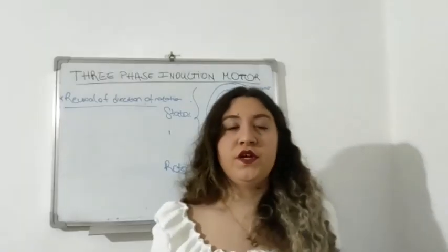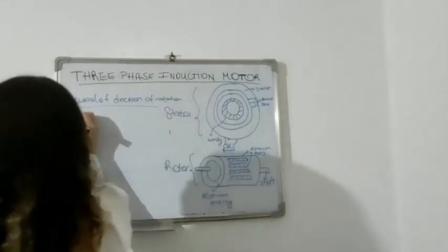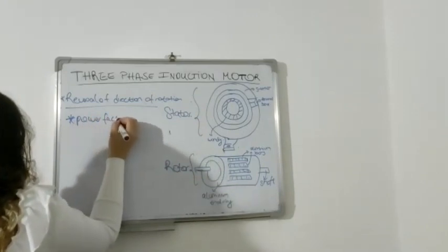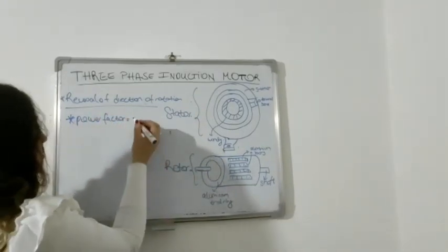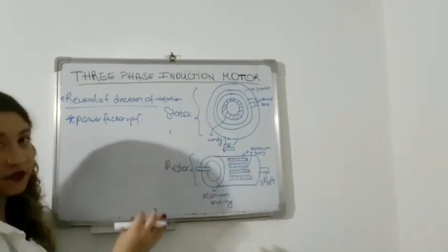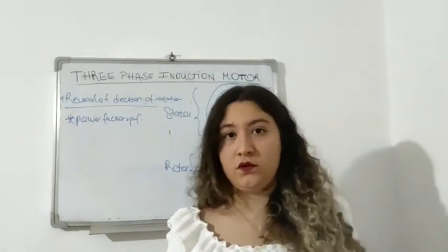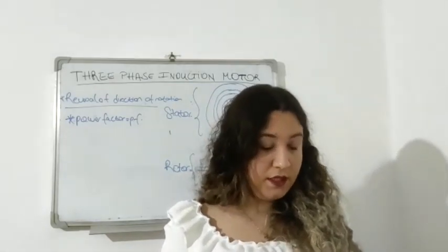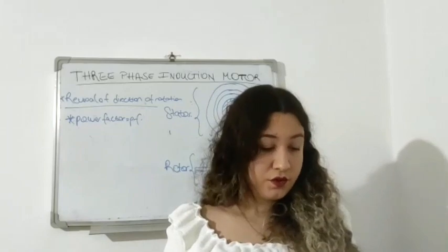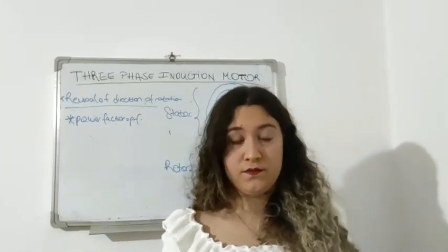And now we are going to talk about the power factor of the three-phase induction motor. We can see the PF like this. The power factor differs between full load and no load in an induction motor. An induction motor draws a large magnetizing current and a small active component to meet the no load losses.